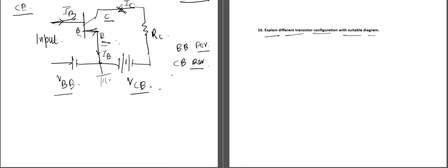As we have said earlier, this is the emitter base junction. When the emitter base junction is forward biased, the potential barrier between the emitter and the base is reduced. So the electrons from the emitter go to the base and the holes from the base go to the emitter. In the base, as the base is lightly doped and it is of P type, the holes will combine with the electrons, which generates the recombination current, which is very low. So the value of IB is very low.